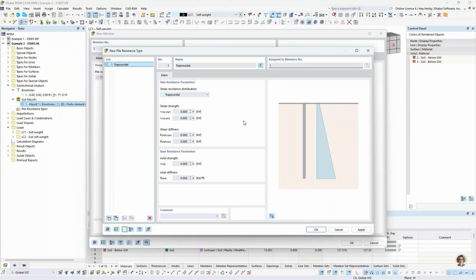Now, this input is just going to refer to the resistance parameter. So up at the top for this pile element, we're going to input the skin friction or the resistance along the pile shaft. And down here at the bottom is where we're going to input the end bearing capacity, or what's the resistance at the pile tip. Now, this information is always dependent on the soils that we have. It's dependent on the geometry of the pile. My colleague gave a great webinar previously that you can refer to where she goes much more into detail on how to calculate this information.